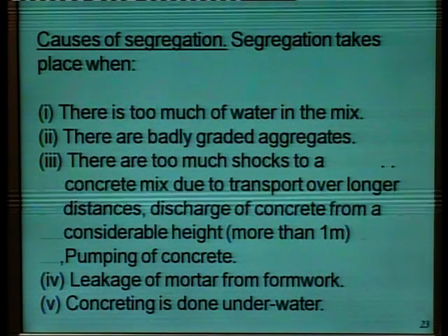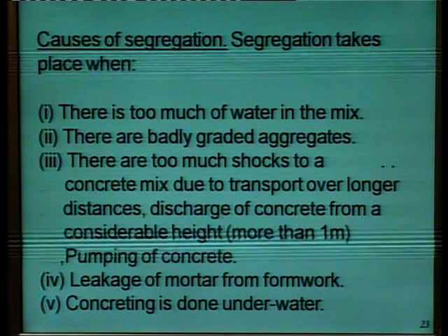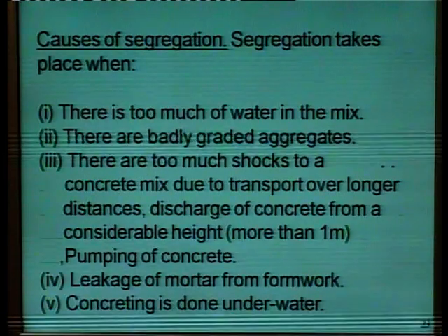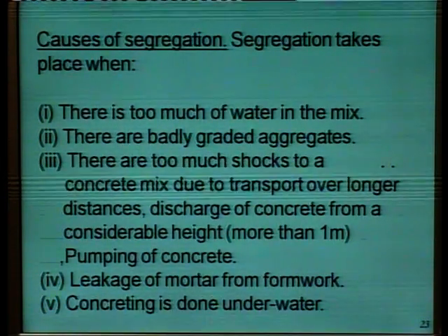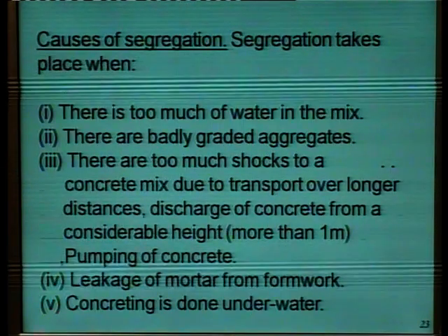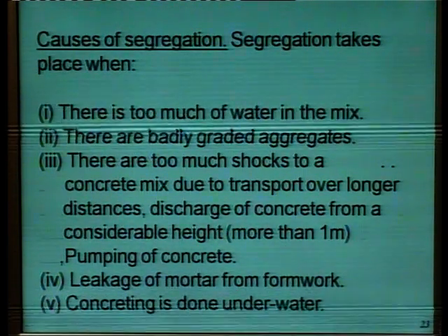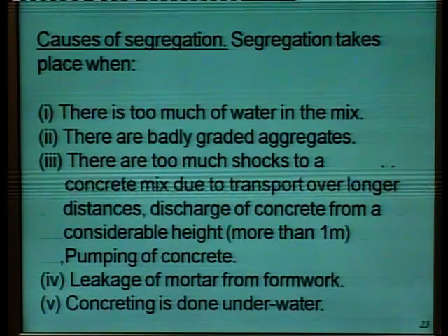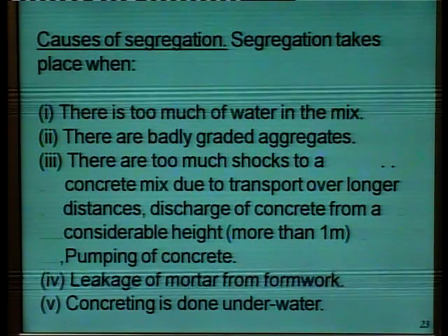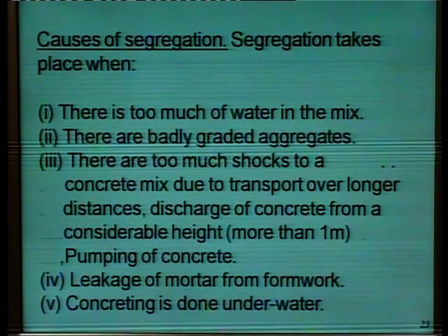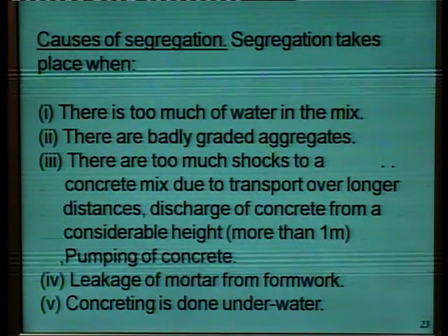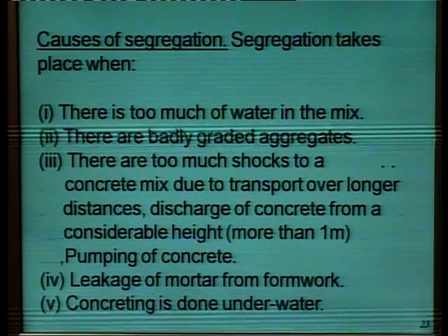Causes of segregation. First is, segregation takes place when there is too much of water in the mix. Second, there are badly graded aggregates.